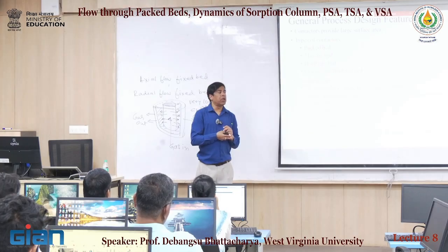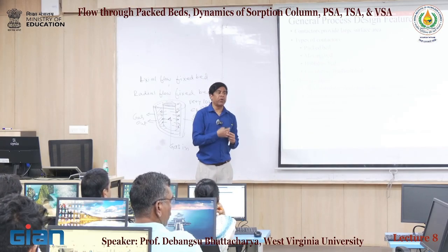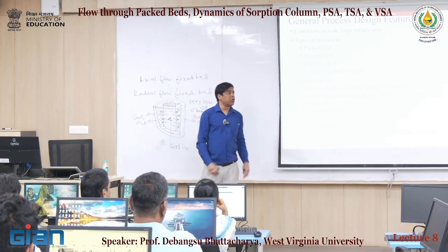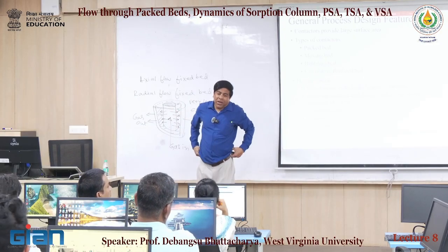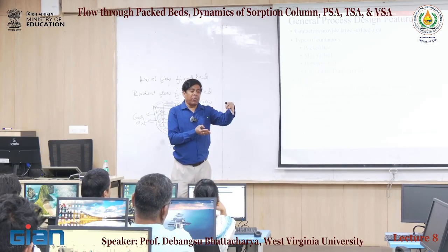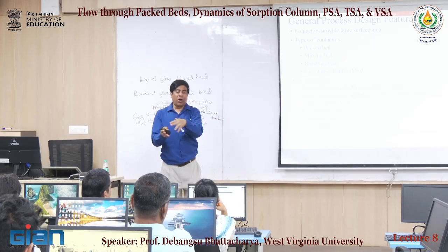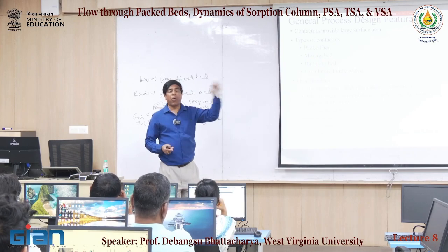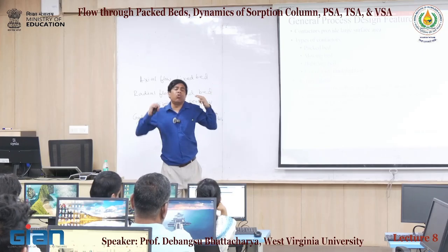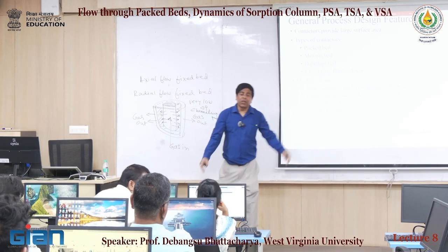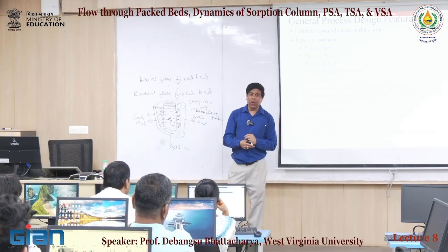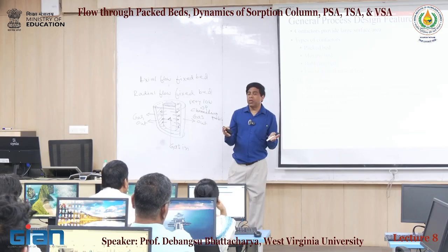The reason why we still work with the fixed packed bed in cryogenic separation is because you are separating CO2 from air, whereas air CO2 is only in the ppm level. So you can afford to have the bed sitting there for a long time and then you take it out and do it. But the problem with these type of systems, like if you look into the power plant, as I was saying, this is like an ocean of gas that is flowing through. So it's 35 or 36 billion ton of CO2 we are talking about. That is where these thoughts have to come into the picture: is fixed bed sufficient?